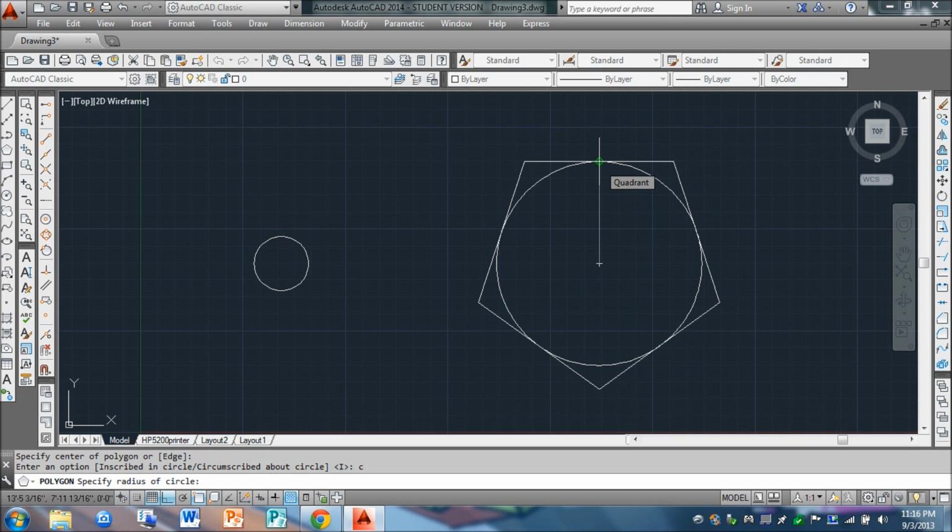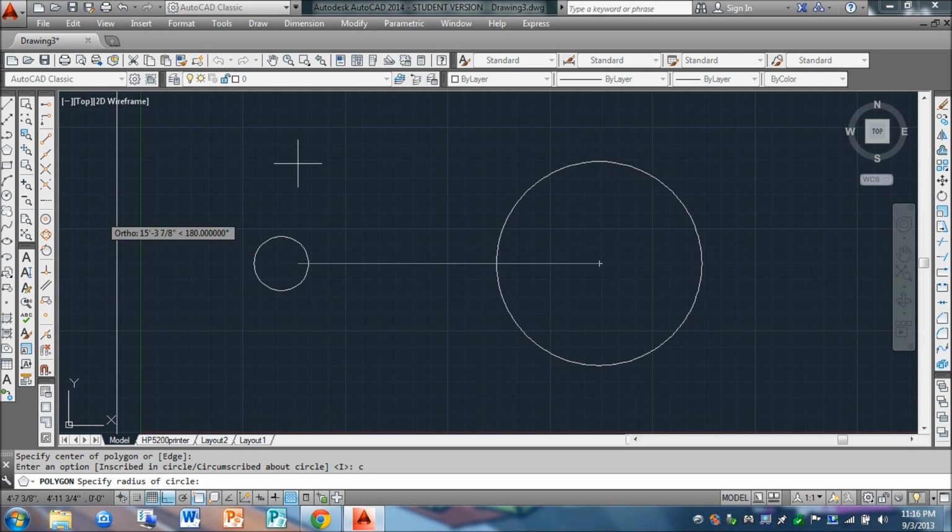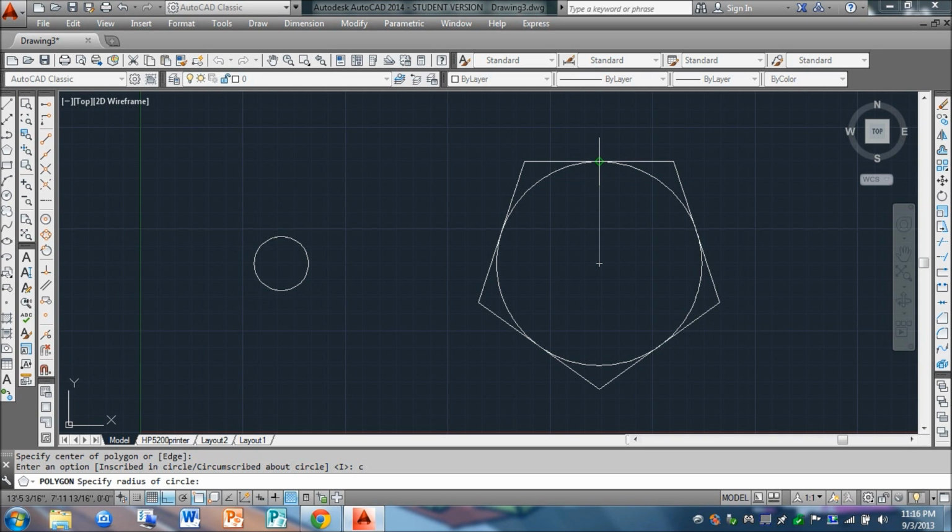So you see how it has the snap on? That is the quadrant snap, the object snap, sorry. Since I already have mine turned on, it's this one here just so you can see. We'll be snapping it to the north quadrant, and we have the beginning shape. This is the outside of the shape. Now to start working with the inside.